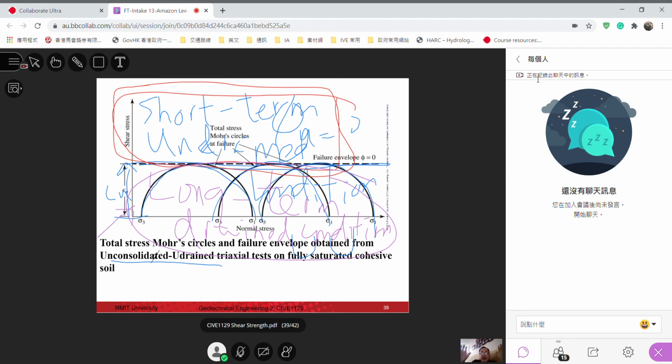So in all geotechnical works, we have to find out both the undrained condition, getting the undrained soil parameters, and also the drained condition, getting the drained soil parameters, and then from that we test both. Later in chapter 4 and chapter 5, when we're talking about slope stability and bearing capacity, we will test both conditions, both drained condition and undrained condition. Then you will realize the importance of doing the right test.